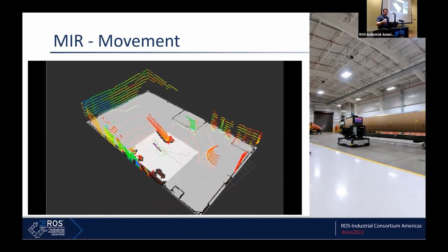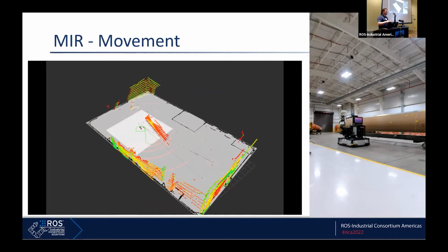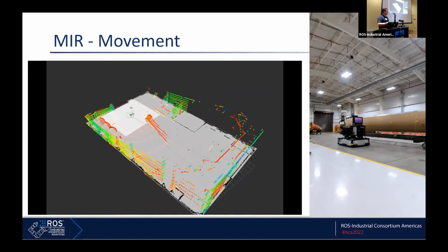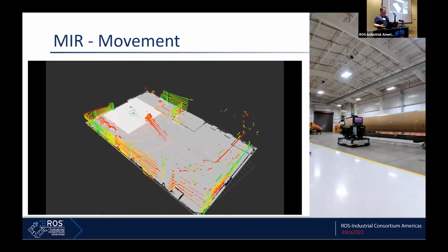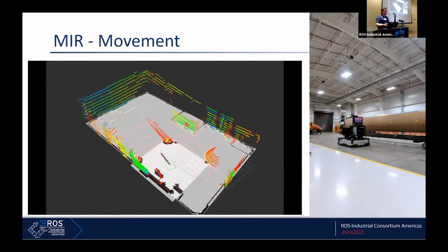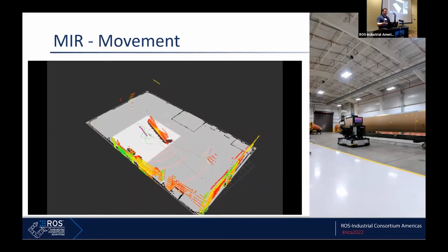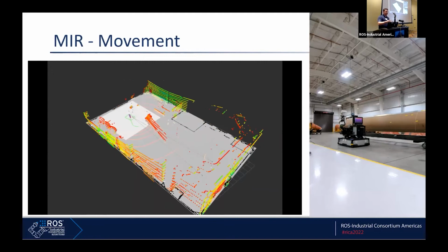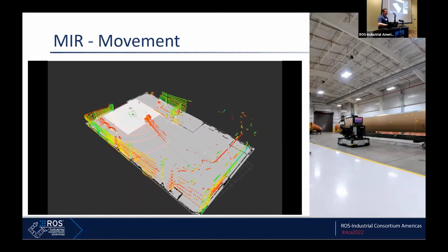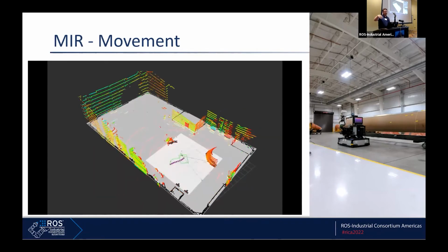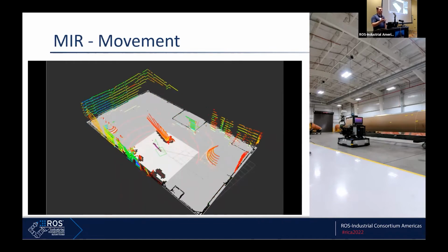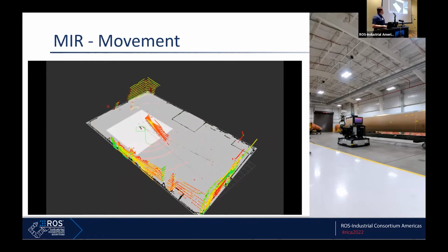So on the right, it was actually the bot driving around, totally automated. The first step of this process was we would take the bot, drop it in, tell it go. It would drive forward, collect that data, then it would do that cropping process that I just described, and then it would step down the length of this long tube so that it could do the robotic inspection on it.